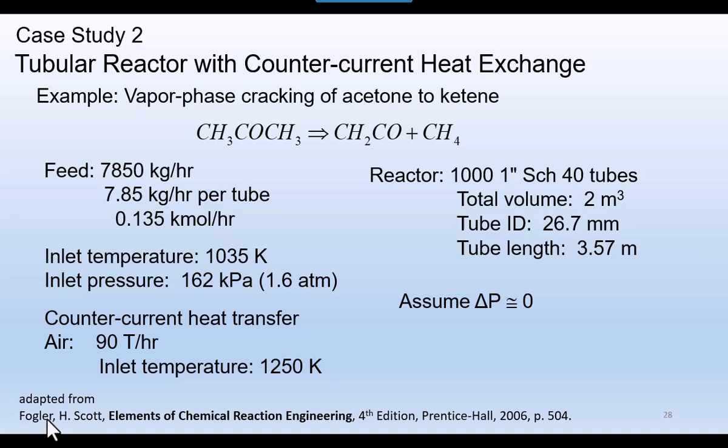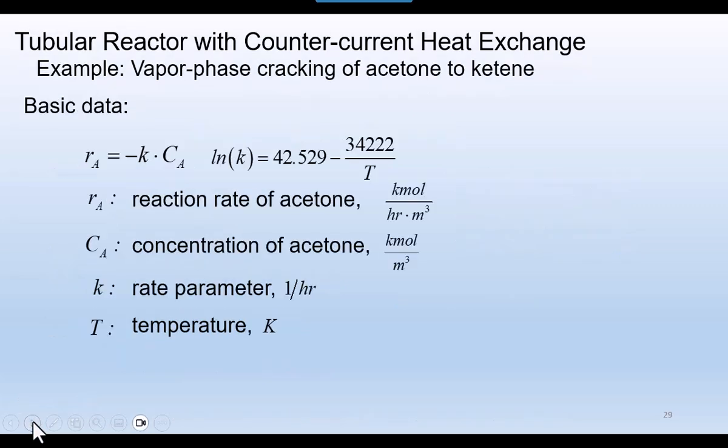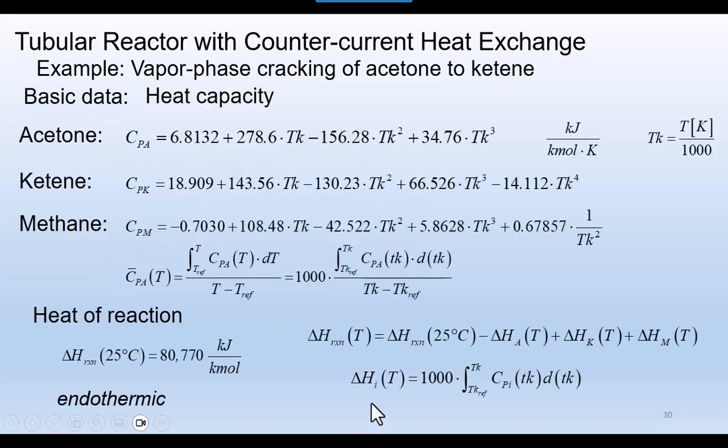So let's continue this and take a look at the reaction kinetics, which are fairly simple, first order reaction in terms of the consumption of acetone, given a reaction rate here in terms of the time units of hours, a rate parameter, and our concentration in kmols per cubic meter. The temperature in terms of determining the rate parameter is provided in kelvins as usual. And then we'll start assembling